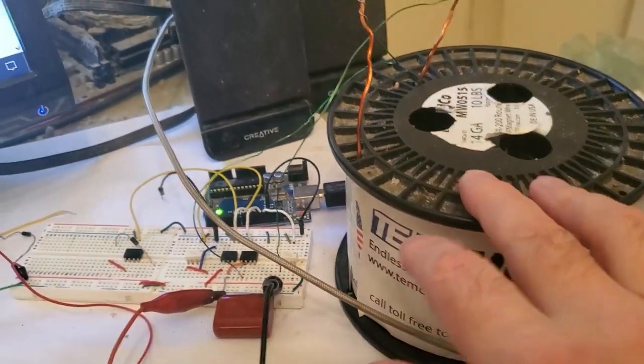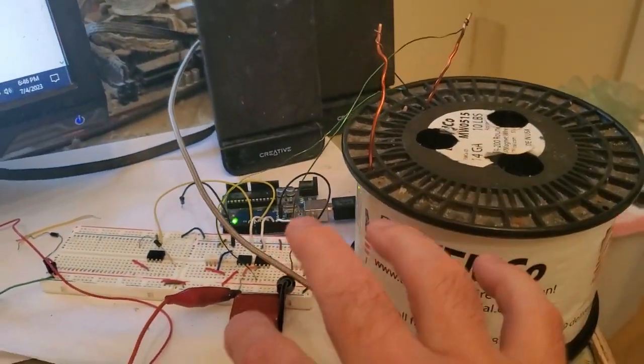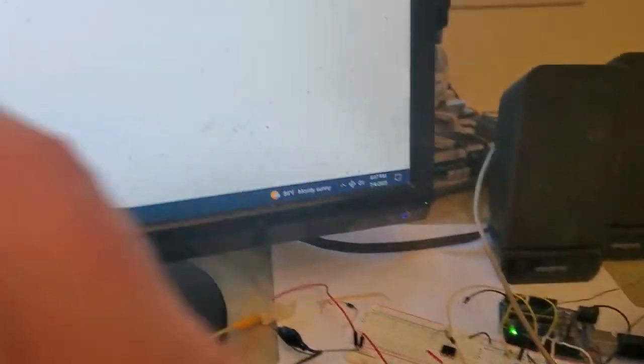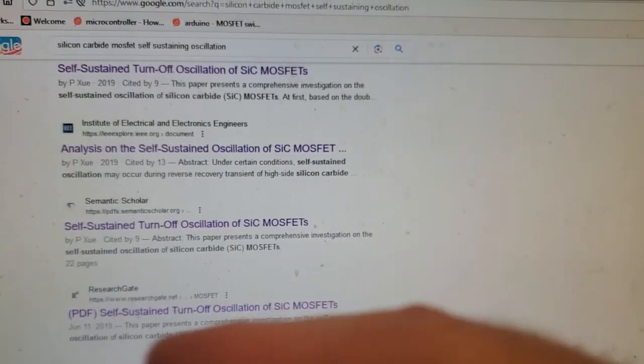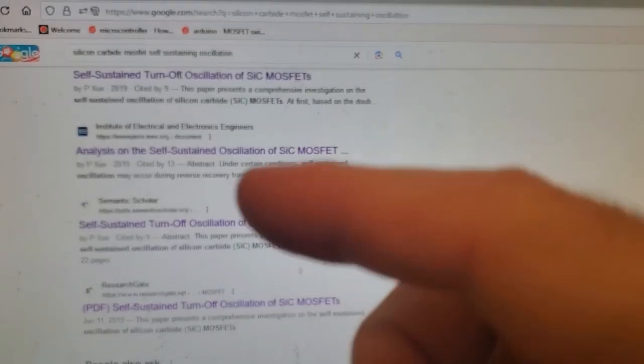The model I would have in my mind for an LC tank circuit like this, with silicon carbide MOSFET, is teeny tiny capacitance and a teeny bit of inductance and next to no resistance. You visualize, or at least I visualize, an LC tank circuit like a child on a swing. If you put in a magnetic air bearing or something, it's just going to swing a long time. But there'd always be some resistance.